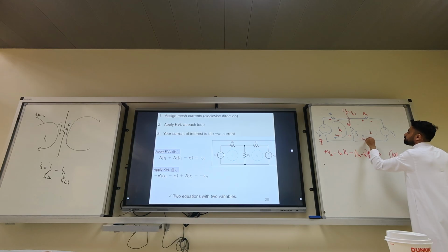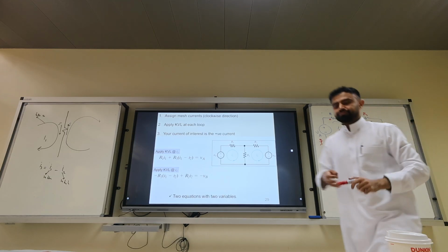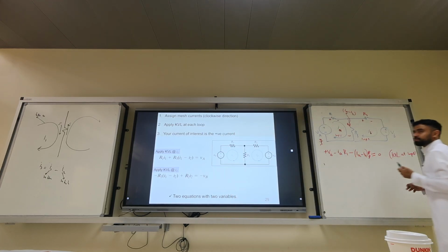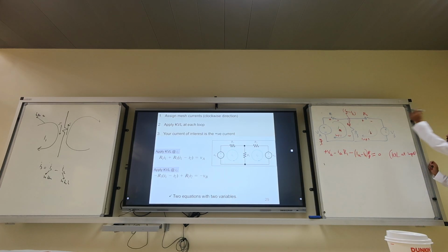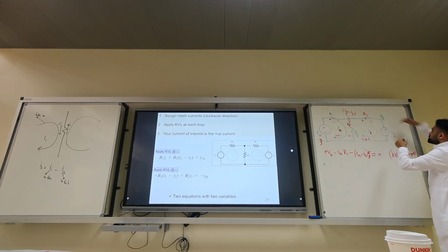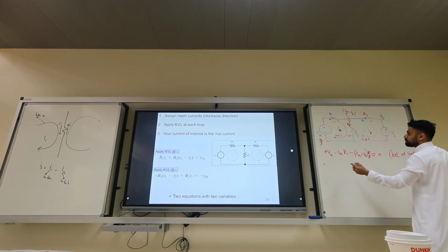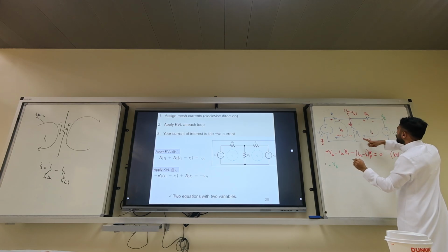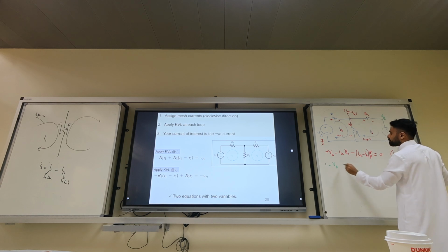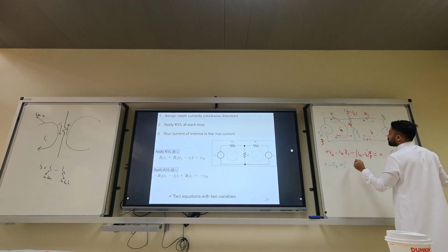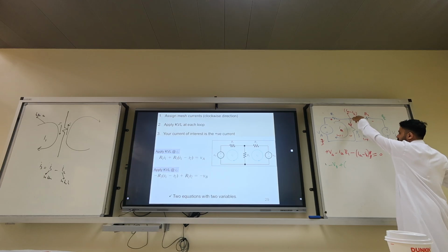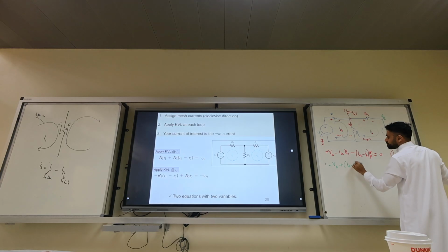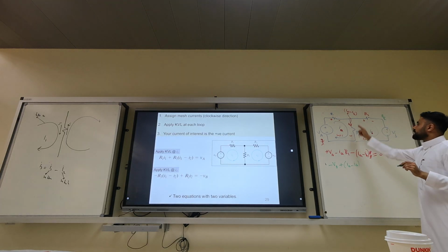This is loop 2. So let's do the loop 2 thing. How to do loop 2? Again, who wants to be the KVL? Srabu. Voltage, go this way. Voltage rise, voltage drop. Minus V. You're here. Voltage rise, voltage drop. Right. Plus. And what's the current that goes here? IA minus IB. Do not say IB minus IA.